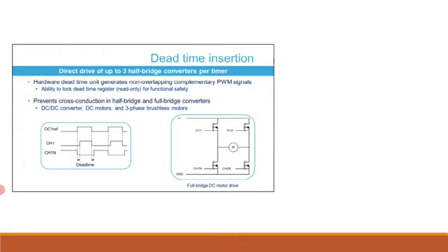Dead time insertion is necessary when driving half bridges, where a pair of transistors are connected in series between two power rails.